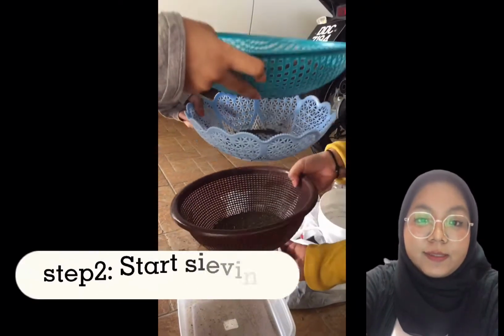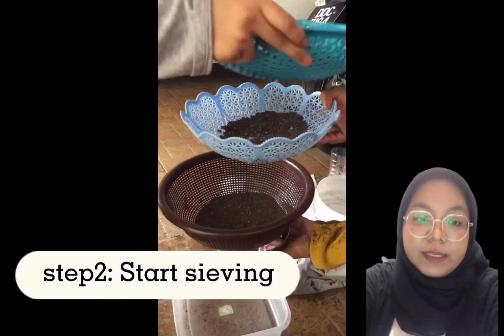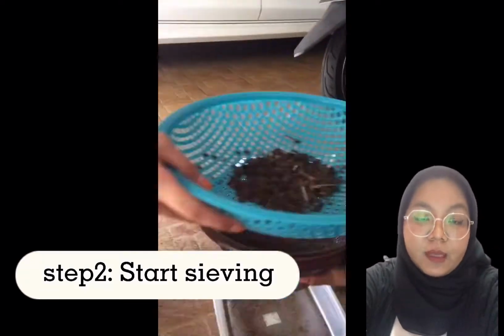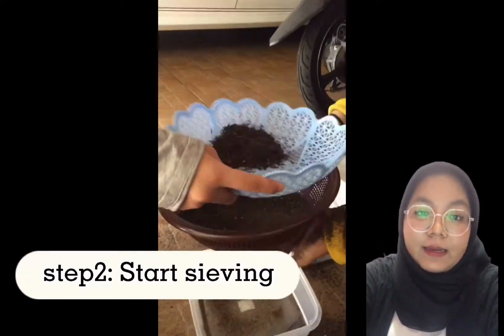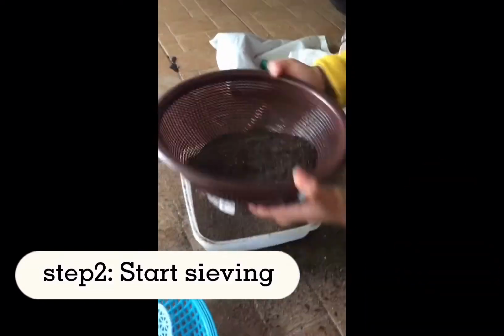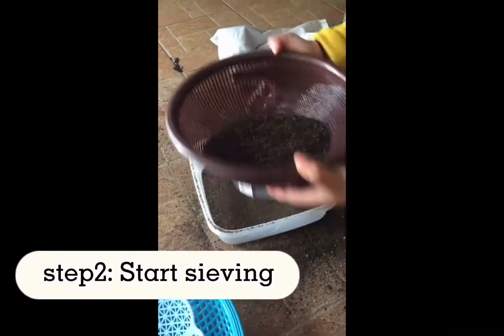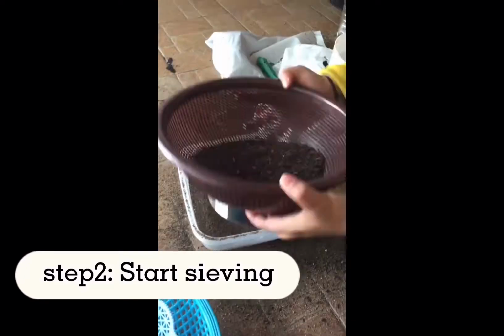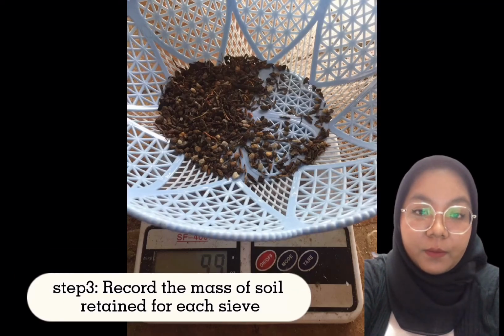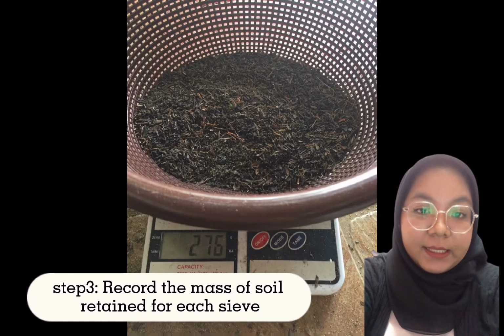Step number 2, start sieving and don't forget to arrange them in increasing sequence of sieve number. Shake for at least 10 minutes. Step number 3, record all the mass of soil retained for each sieve.